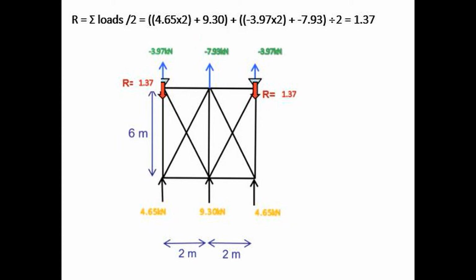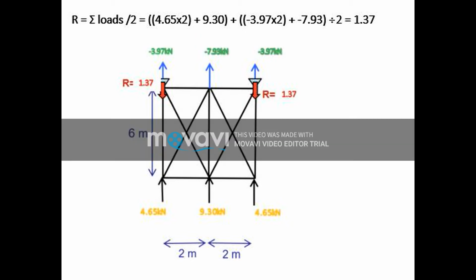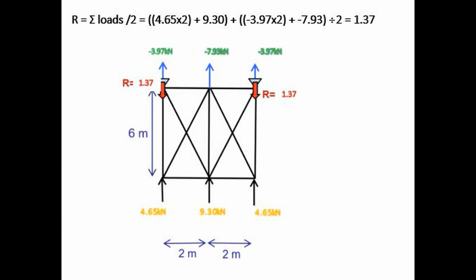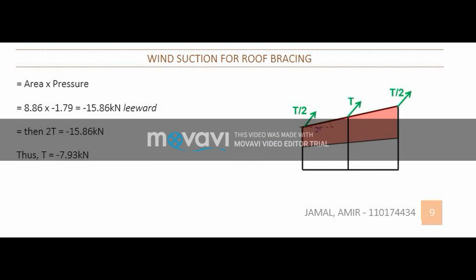After the bracing layout was determined, determining the height of the shorter wall of the shed was a quick task, which was calculated easily due to the roof of the shed being a skillion design. Then we had to find the half and gable surface area. Using these values, we then find the wind pressure for the roof bracing and also the wind suction for the roof bracing.